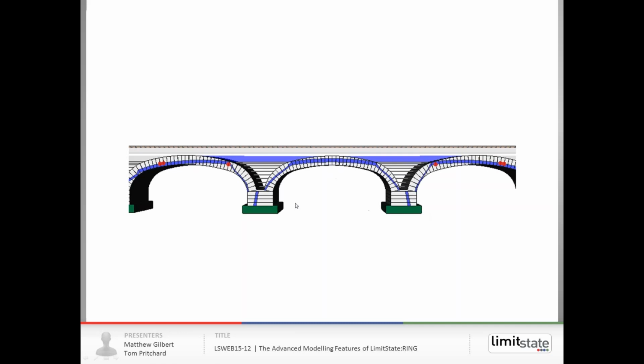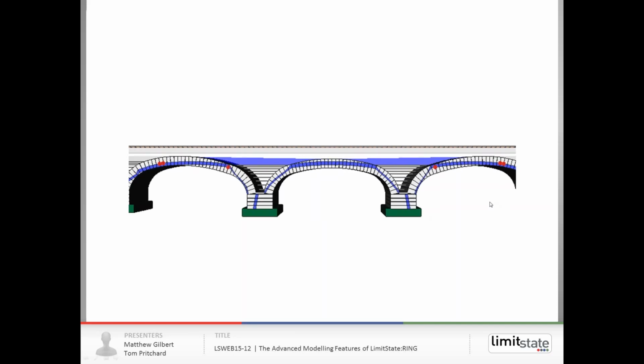The first model that I developed using approximate geometry looked something like this. The key thing is that the hinge positions I got from the model very closely approximated those that we saw in the field. To build this model, I'd assumed that we have backing material above the piers up to approximately the level you can see on the slide. So that appeared to be a reasonable model of the structure.